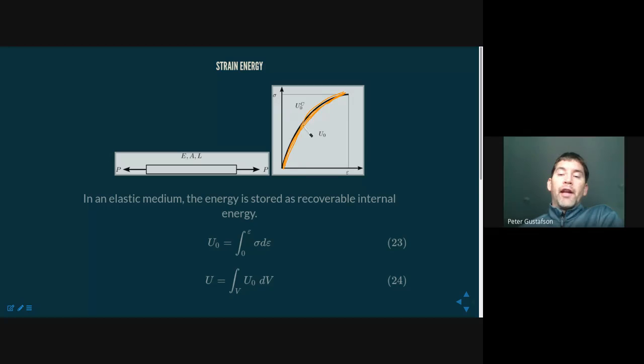That is a conserving principle. If you are in an elastic system, you go up and down the same path. If you get into a plastic zone, if you have plasticity, then you unload along a different path, and actually energy is consumed in doing damage to the material. And that is going to be an irrecoverable energy. So we're not going to talk about that much for the time being. That's the domain of a future lecture, perhaps in a future course. But for an elastic material, the key is that it unloads along the same path, and so all the energy is recoverable in an elastic material.